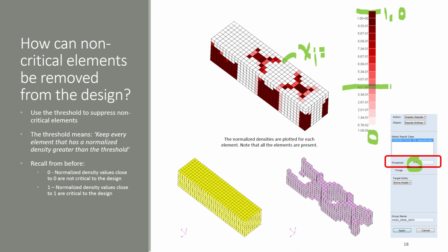So here, what we're saying is everything above a 0.4, anything with a score or normalized material density of 0.4, you should keep that. And this is what was shown here in purple. This is the final solution. Sometimes, just in case 0.4 isn't enough, you can also use 0.3. Generally, you want to use a threshold greater than 0.3 or 0.4.